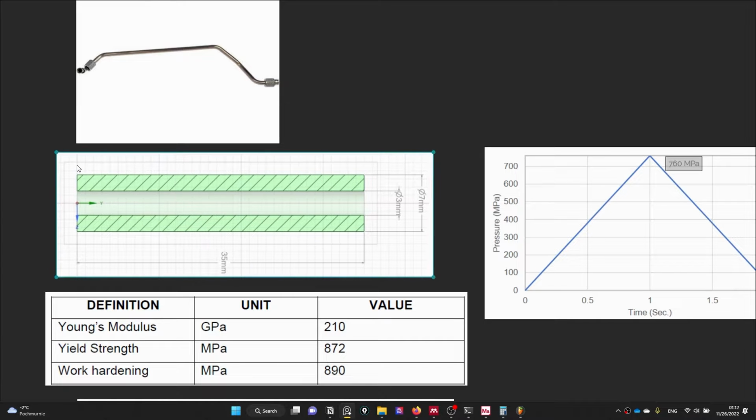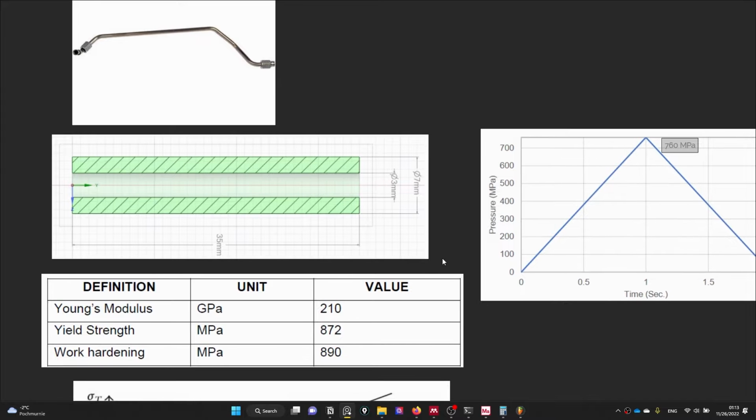because you know the water jet cutting machine works under very high pressurized liquid water, and this liquid is pressurized with hydraulic pumps. The pressure is around 500 megapascal, even higher, and it is conveyed by a tube, and this tube has dimensions around this value. Therefore I selected these dimensions.